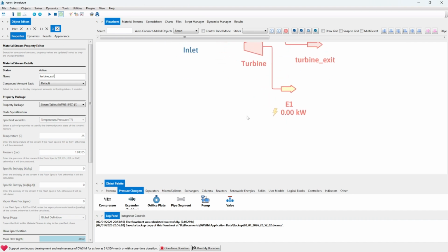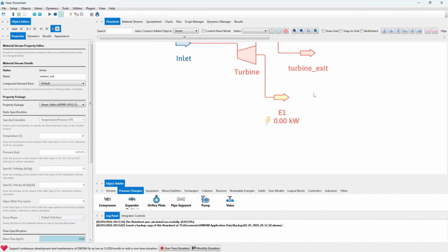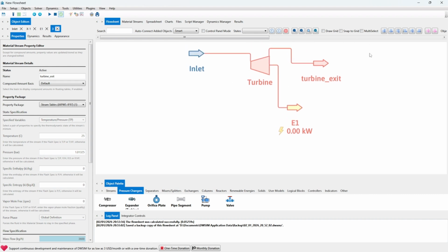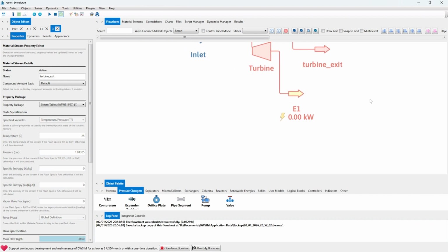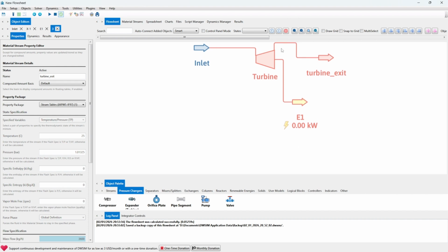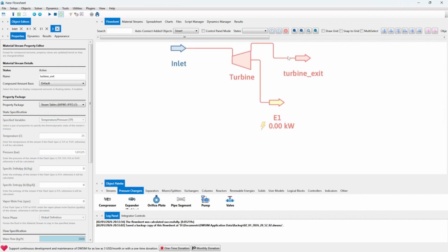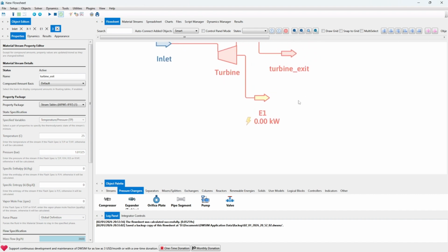From there we need to condense this liquid, since it's going to be a loop and we care about the enthalpies. Unlike the Carnot engine, where we just dealt with the efficiency from the temperatures of the inlet and the outlet of the turbine, in Rankine you're going to deal with the overall efficiency of the entire cycle, and that will deal with the enthalpies. So first we need to take this steam and condense it purely.